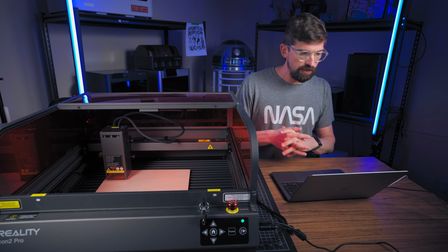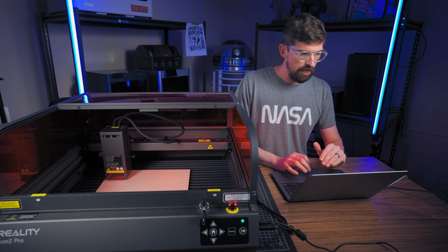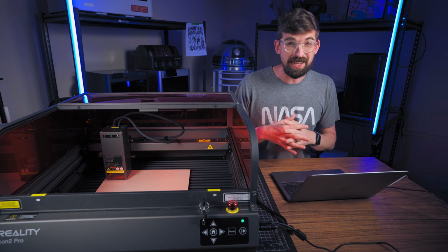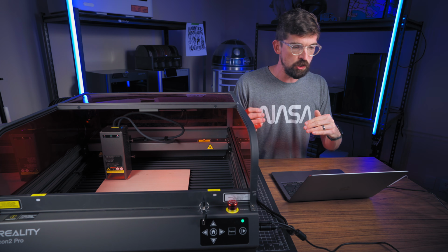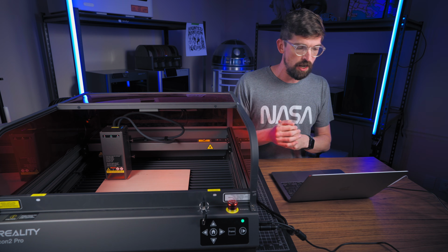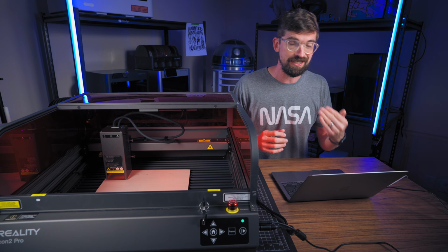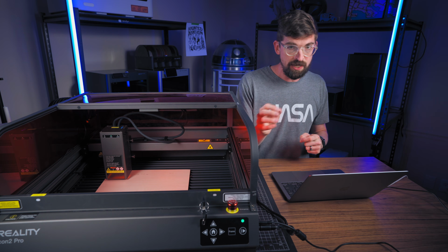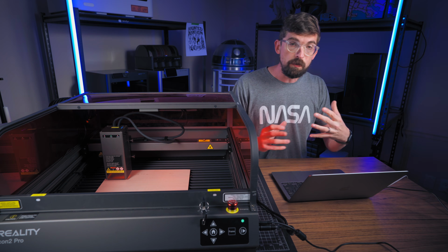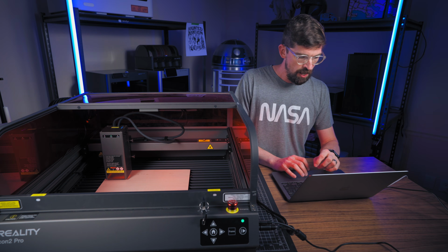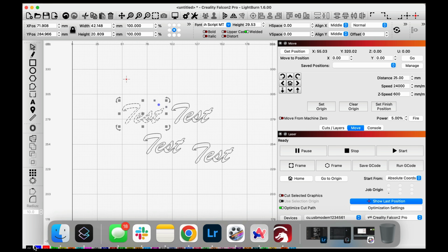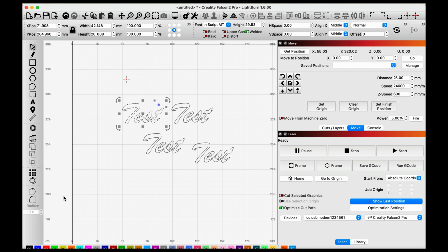And since we got a few things in here as well, let's talk about grouping really quick. We're gonna talk about layers here in a minute, and you're gonna think about layers a lot differently than you would in a program like Photoshop, where things are layered on top of each other. Typically, you're gonna use layers to have specific laser settings. So feeds and speeds, as well as fill settings, will be within a single layer, but you can still group things within a single layer. So actually right now, since everything is showing up as black, I've got my layers turned on, but the Mac screen is cutting them out a little bit, but you can see they are labeled down at the bottom.